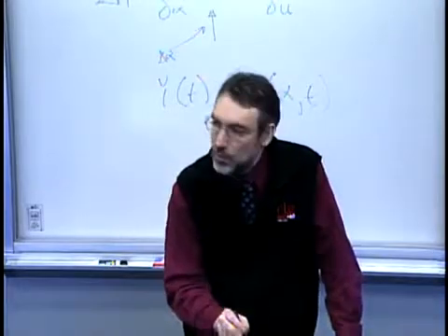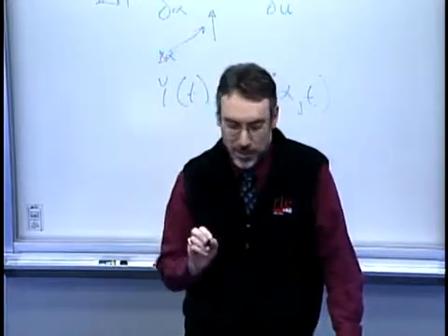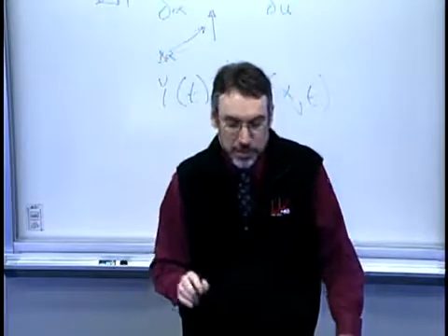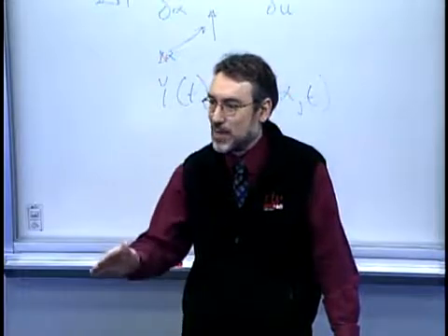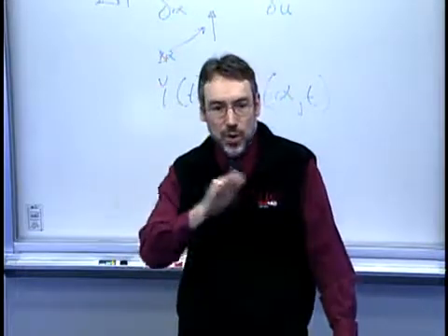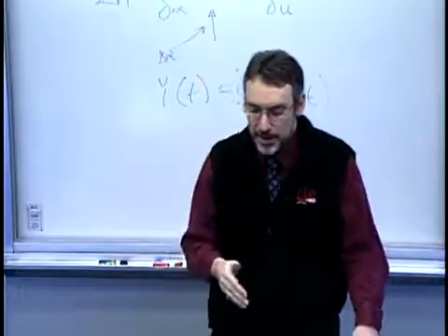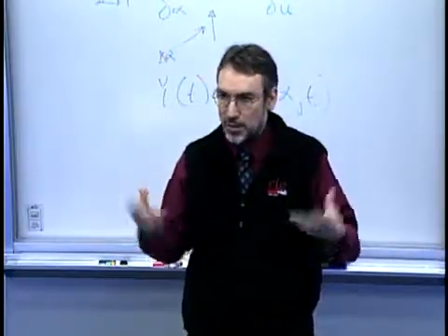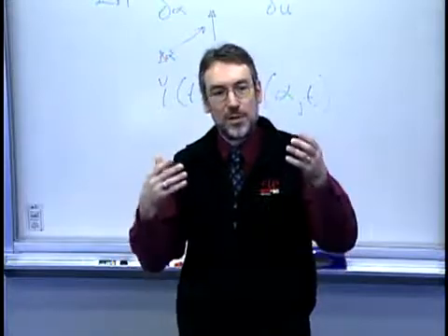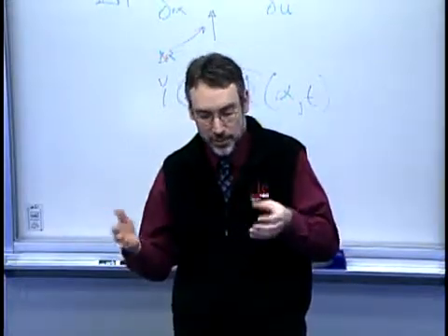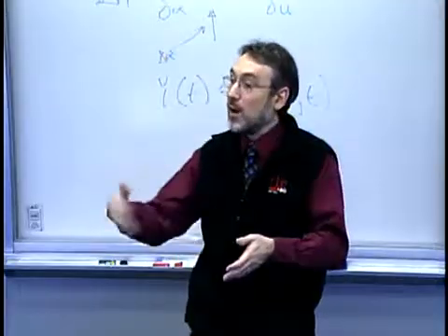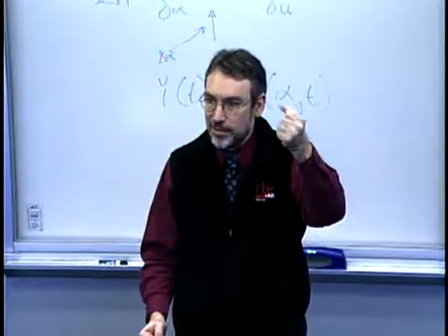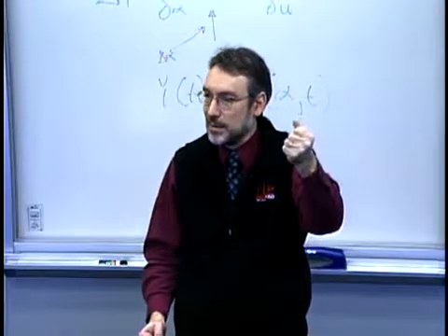And when there's something systematic or deterministic going on, the whole idea is you make some changes to the equipment to stamp those out. What we're often going to be dealing with is designing experiments to try to understand systematic components and eliminate them, maybe as part of the initial design implementation of a process, or in an ongoing process, when we see a deviation, we have to debug it, find out what caused that, and eliminate it.